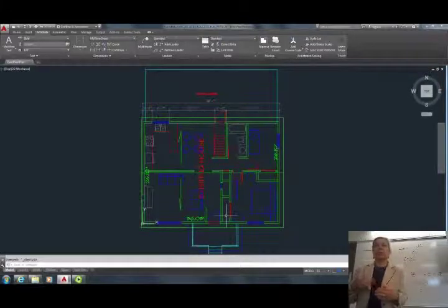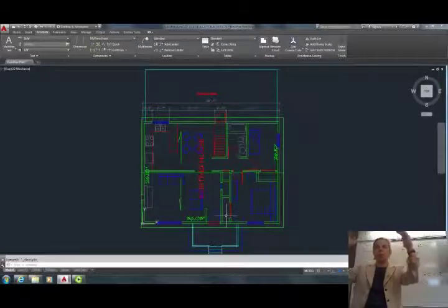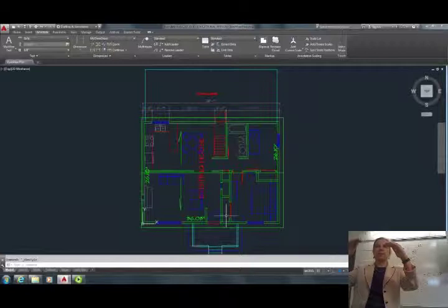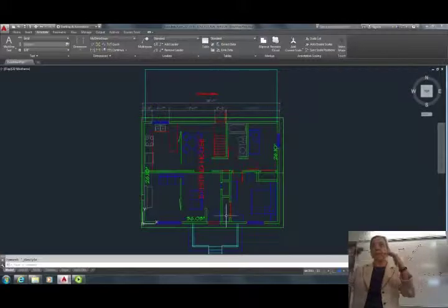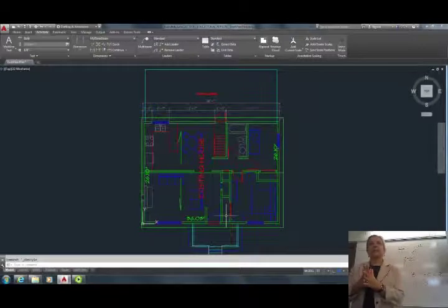So this is how you remember that if you have jogs in the building, you would have overall, then about 1/4 inch down, you would have jogs in the building, outside to outside corner of the frame, and then, last but not least, openings. There are two ways of doing dimensions for openings. Some very quick construction drawings, builders especially, they will dimension to the center of the window, and I think that's what Steen is doing in his textbook. Whenever I designed houses, I always specified dimensions of windows I wanted. Because if you dimension to the center, you're giving the builder an option of putting whatever window they can find cheap.